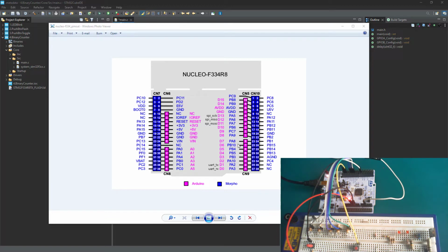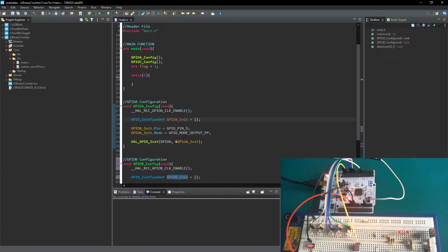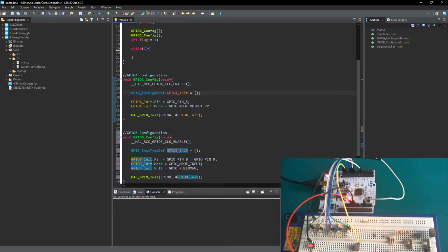So basically what it means, I've got 5 pins there, and the 5 pins are GPIO 4, 5, 6, 7, and 8. So just like I've done here in the port B configuration, I'm also going to use an OR operator to configure this GPIOA configuration.